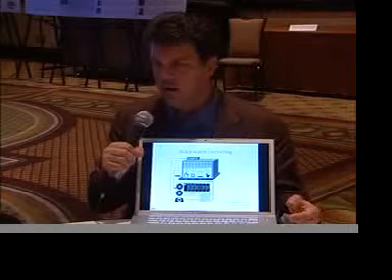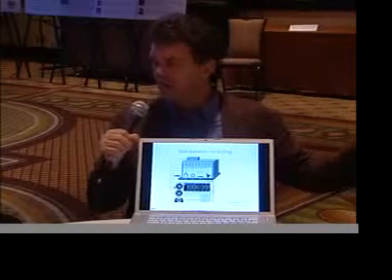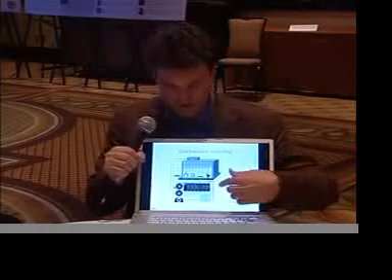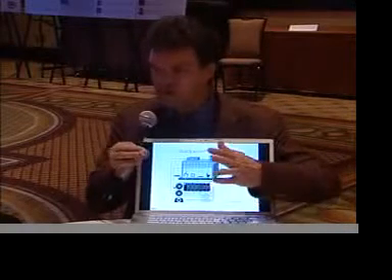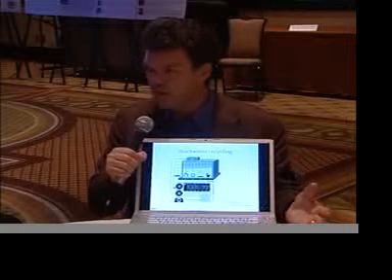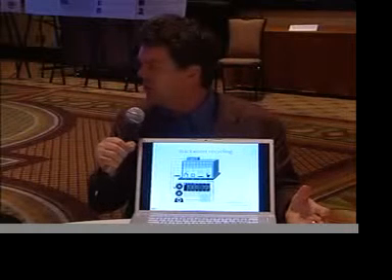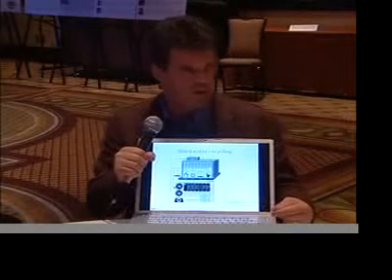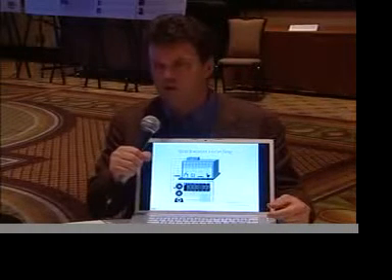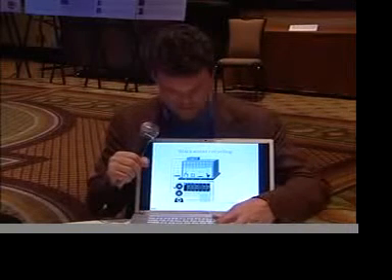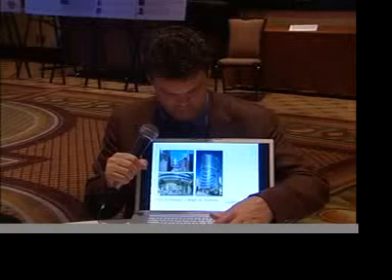What we've seen over the years is that municipal scale schemes have been scaled down for this application. When you've got the sewer as a backup, you can remove a whole lot of redundancy. You can take the system down for maintenance, which you don't have the luxury of in a municipal sewage treatment plant. So these are the sorts of design philosophies that we introduce into what we do, just to cut down on the cost. And it's about being practical, really.